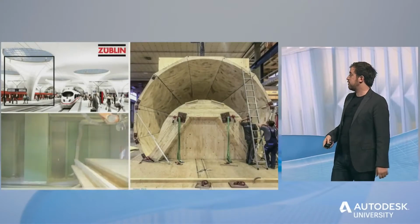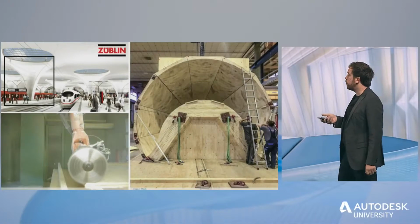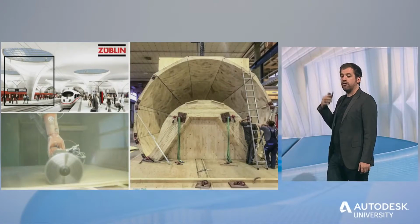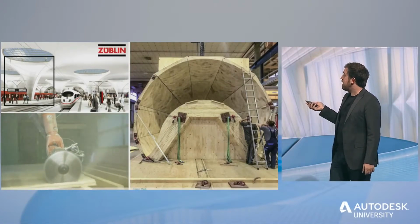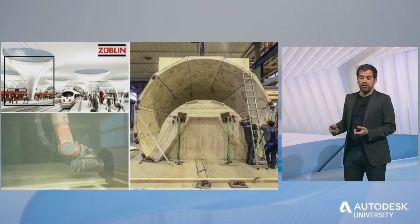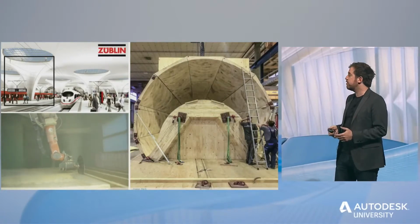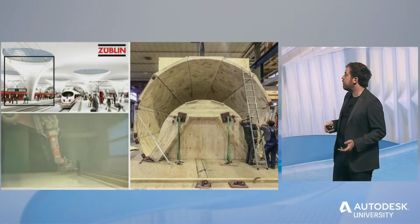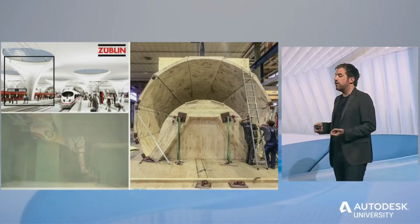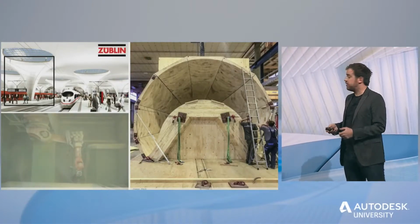So processes like this are, for example, used on a large scale for timber manufacturing, what you saw before. You see we have this wooden formwork for free-formed columns, and all of these elements somehow look the same, but again, each one is individual. If you do this with a normal workflow, you have to treat every element as an individual shape, and it takes up much time. But if you think about it more cleverly, you think, well, actually I only have to program it once, and then the parametric model is going to adapt accordingly. So it's not much more effort if we do it once, or if we do it like 500 times.